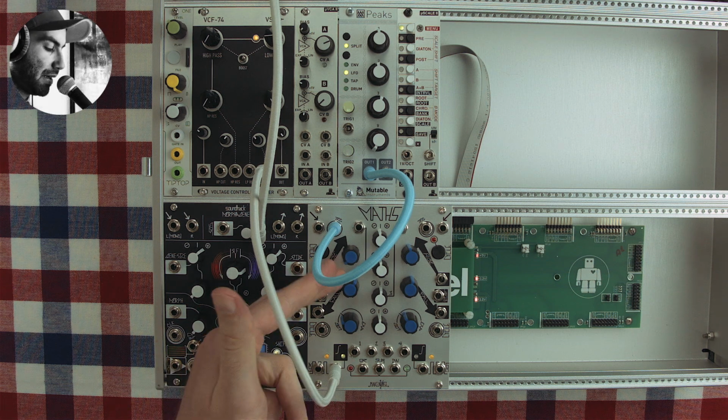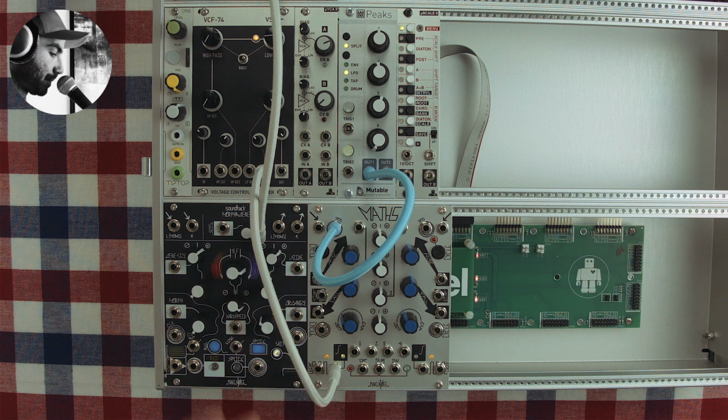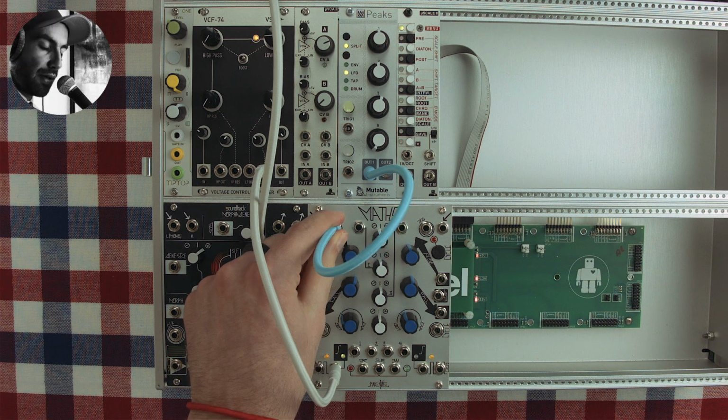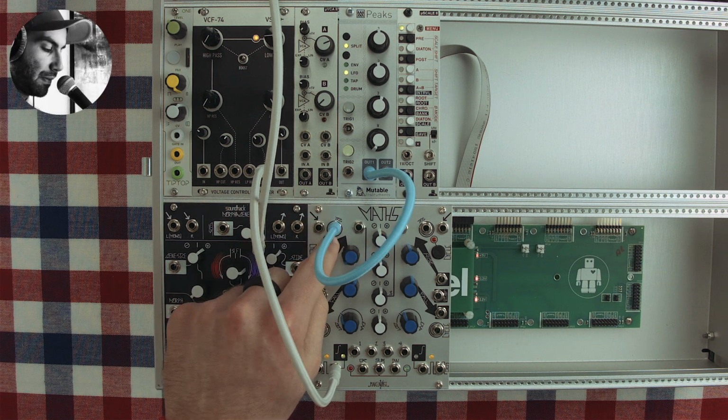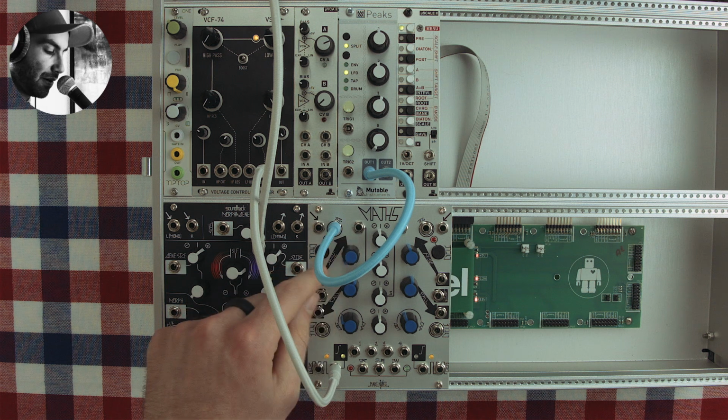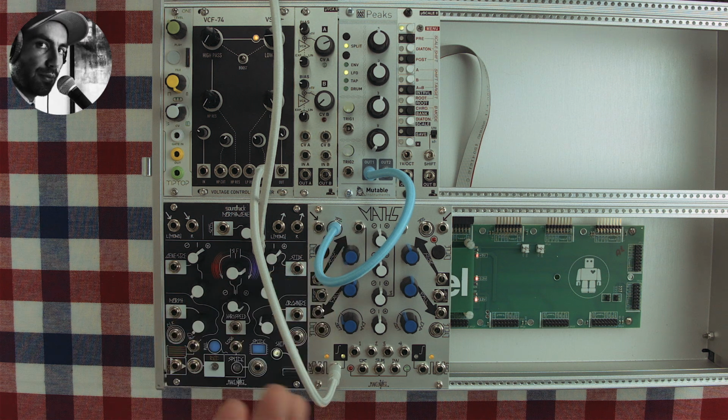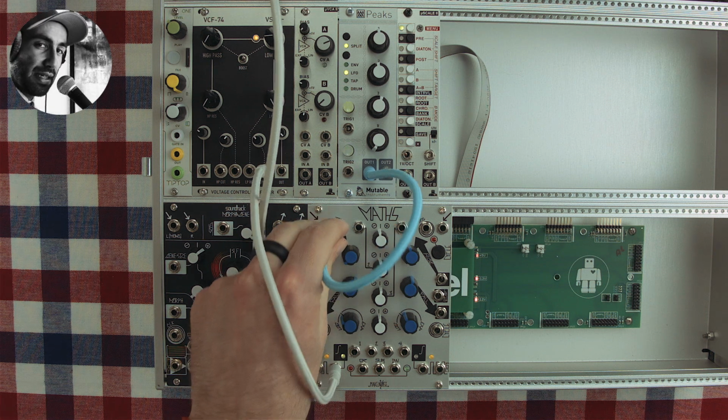What that basically means is that every time it receives a trigger, it'll kick off a function cycle. So you can treat it as an envelope generator effectively. Except the difference between a standard envelope generator and this trigger input here is that as soon as it receives a single trigger, it'll complete entire cycles. So it'll go from rise up to 10 and then back down when it reaches 10. Whereas in a standard ADSR envelope generator, as long as the gate is high, it'll remain in the sustain stage. In this case, we don't have the sustain stage.